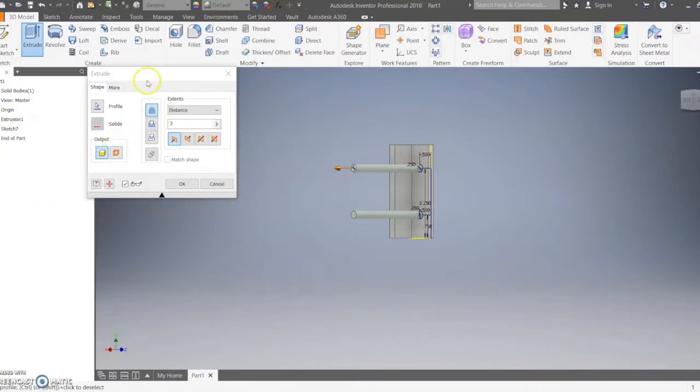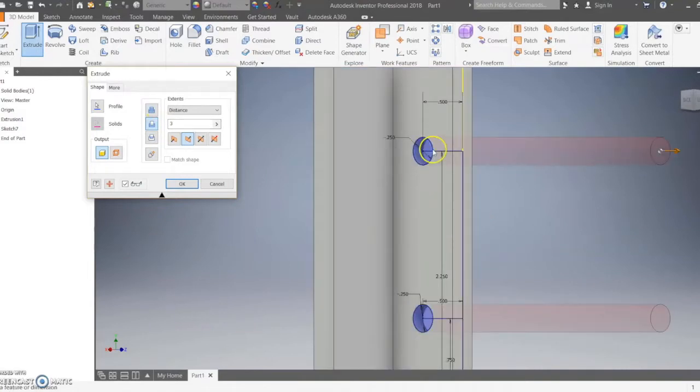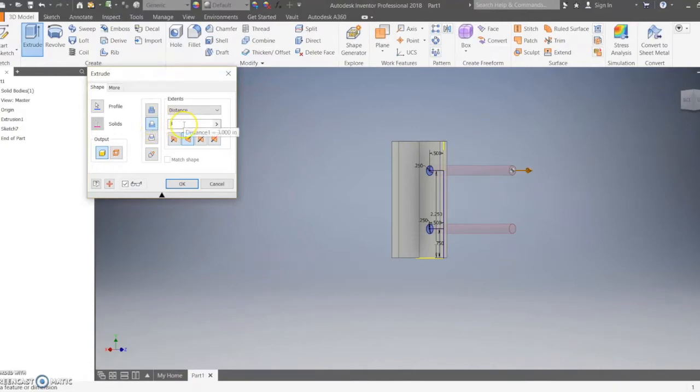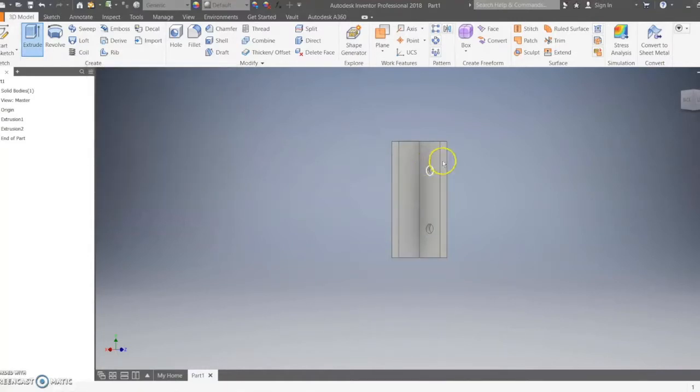So there's actually an option under the Extrude panel called Cut. Cut basically, instead of adding to the part, it cuts in the opposite direction through the part. So if we press Cut, you can see that it reverses direction and it actually goes through the part, leaving this hole here, which is what we want. So choose the Cut option, and in this case, it's 0.125 thick. Since we're just cutting, it doesn't matter if we go more, but it's better to choose the exact distance you want to cut for more precision. So we choose 0.125 and we press Enter, and those are our first two holes.